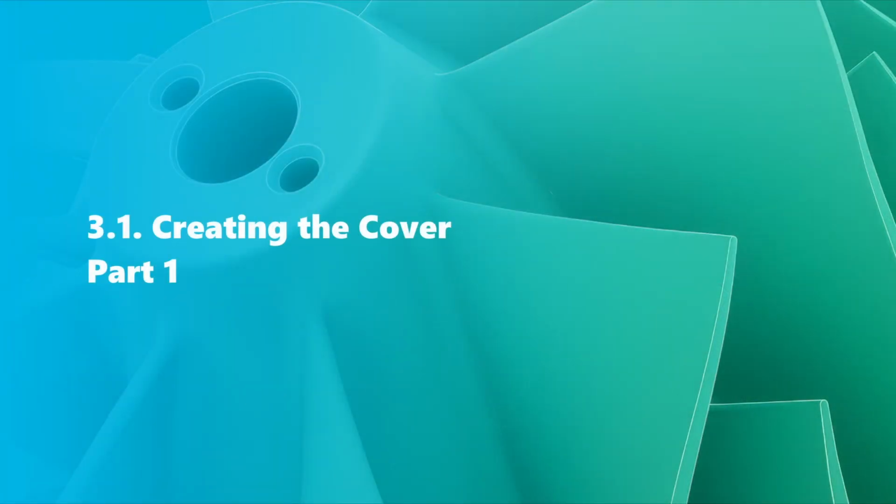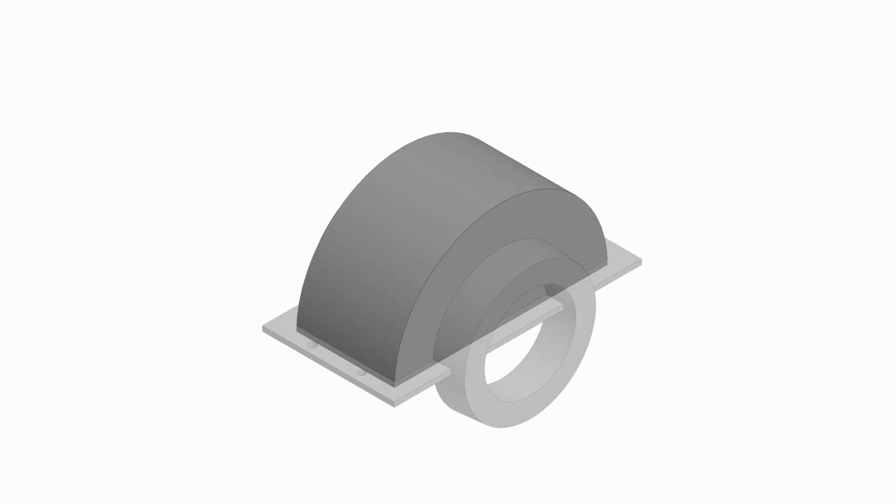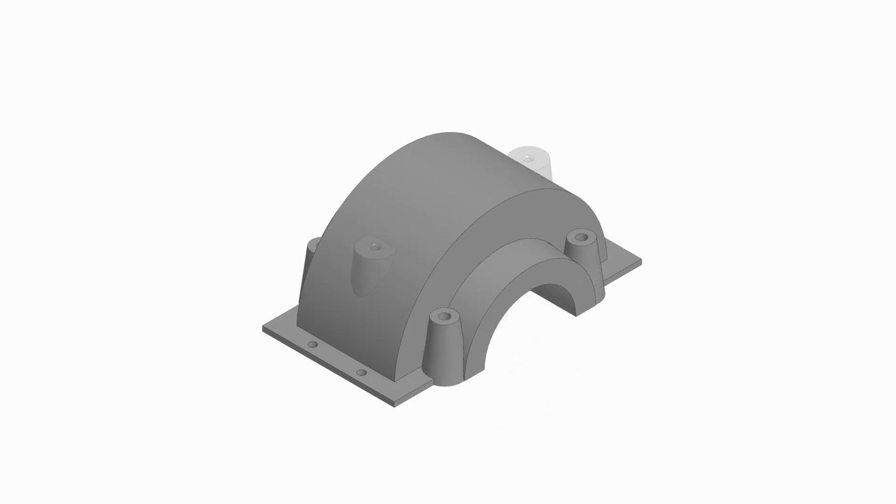In this lesson we'll start creating the cover from scratch based on the layout geometry. We'll create the cover base using standard commands and add the conical bosses with holes to it.